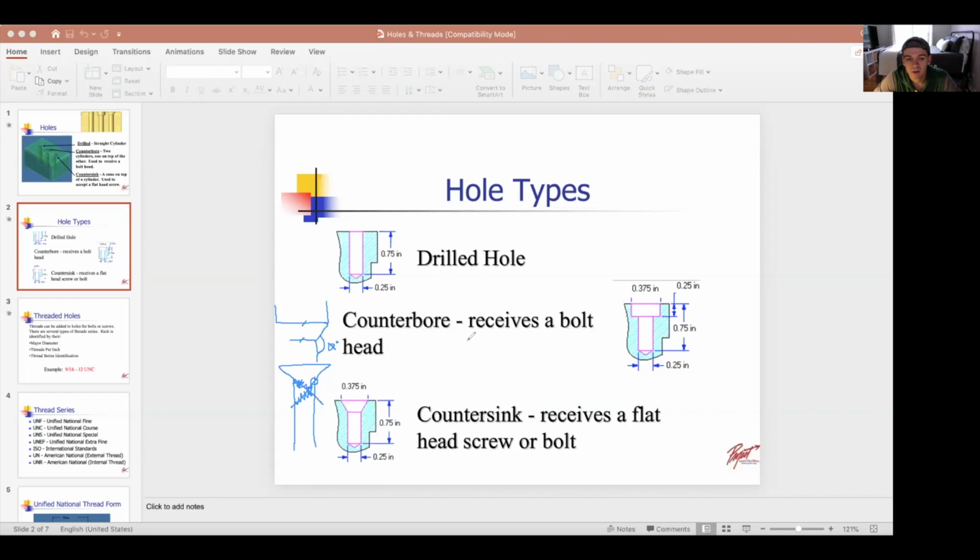Sorry. Okay, and then your next one is a counterbore. Now here they show the distance to this line, but no angle, obviously, because it's just straight up on here, but it'd just be a cylinder in a 3D view. So then you have your heights there and your diameters or your widths there.